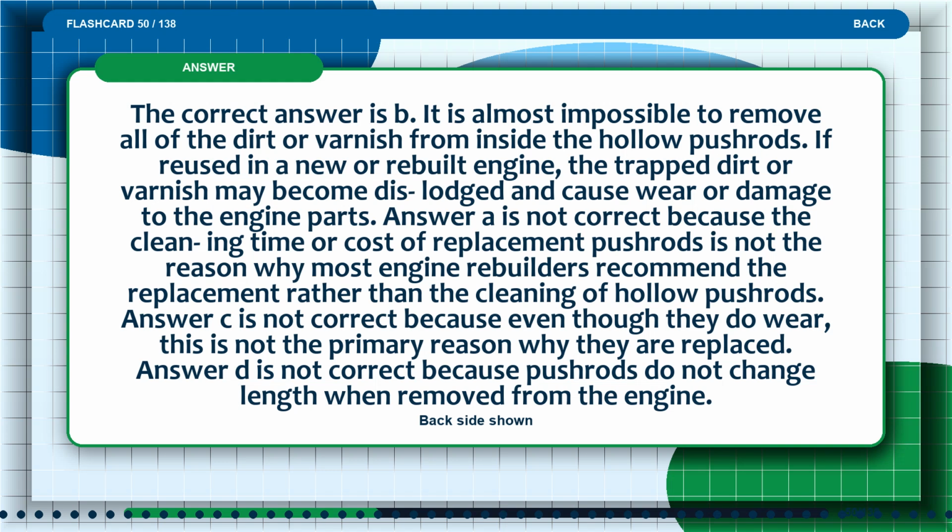The correct answer is B. It is almost impossible to remove all of the dirt or varnish from inside the hollow pushrods. If reused in a new or rebuilt engine, the trapped dirt or varnish may become dislodged and cause wear or damage to the engine parts.